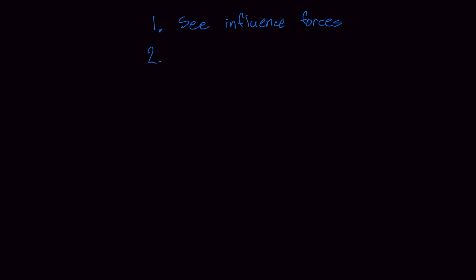Then I will find the critical location and resultant moments. Because usually in parts like this, the bending stress is going to dominate. So it's really important that we find the resultant moment and where that critical location is.